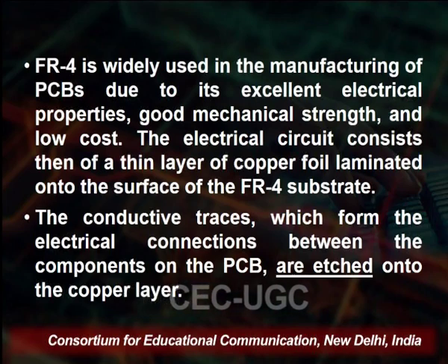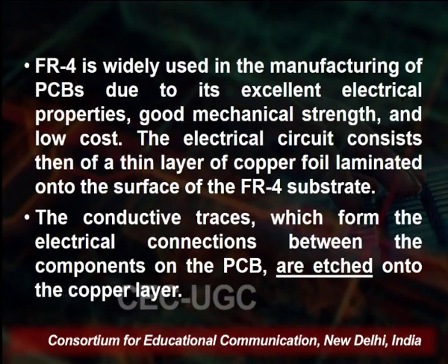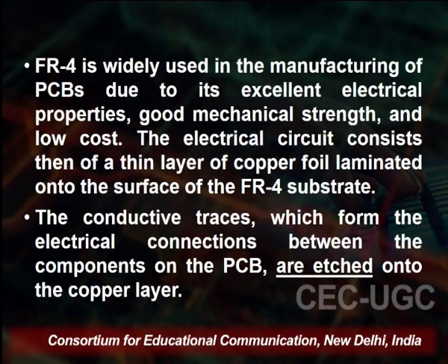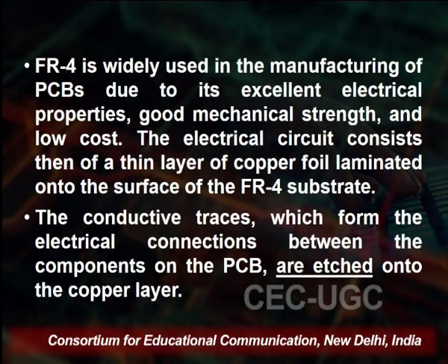FR4 is widely used in the manufacturing of PCBs due to its excellent electrical properties, good mechanical strength and low cost. The electrical circuit then consists of a thin layer of copper foil laminated onto the surface of the FR4 substrate. Conductive traces, which form the electrical connections between the components of the PCB, are etched onto the copper layer. So substrates ensure that these traces remain insulated from each other and from the surrounding components, preventing short circuits and ensuring the proper function of the circuit.